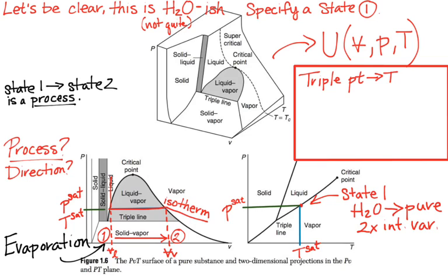So there are some key states in here where temperature and pressure are not independent of each other. That would be at the critical point and at the triple point. You see that both are basically dots. In this case it's a triple line, but the critical point is the key point that we think of. In table B1, the temperature table, you go to the bottom of that table and you're going to see the critical point temperature and the critical point pressure.